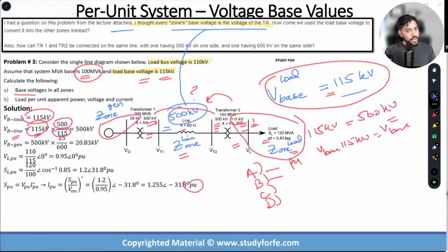So now when I fix 500 kV over here and I have to figure out the zone voltage here, what I'm going to do? I'll take my 500 kV. I'm going to the primary, right? It is to the primary, put that on the top, which is a 25 kV for this transformer, and the secondary of this transformer is 600. So that gives me 20.83.